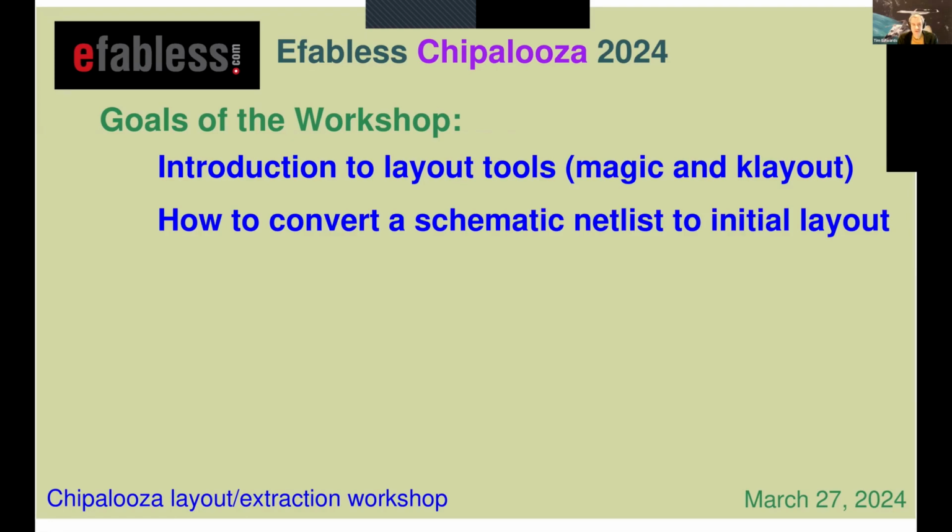Also, how to convert a schematic netlist to the initial layout. That is the most important for the Chipalooza Challenge participants. They have got their netlists in either ready condition or close to it, in most cases, and are ready to get it into layout. And I do have a method in Magic for going into an initial layout. I do not have a method for creating your layout automatically.